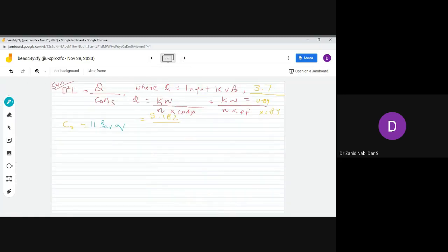So this is ampere conductors, AC or Q, whatever you want to write, you can write kW in 10 power minus 3. So rest values we have, BAV value we have 0.45, Q value we have 2300. You have the value of kW as 0.955, then you have 10 power minus 3. So you get one particular value, so it would be around 108.73.